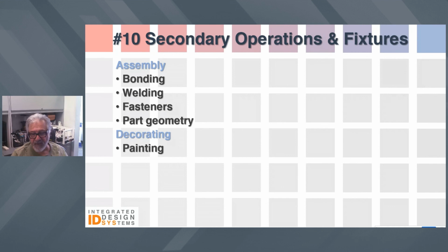And in the area of decorating, you've got paints, and paints have to be compatible with the substrate and the surface preparation of the part. So the parts have to be cleaned and devoid of any type of release agents or contaminants on the surface, so you get a nice, clean, uniform paint finish. Plating is another decorative, commonly applied method of decorating plastic parts. Then pad printing, and although it's very versatile, the alignment of all the colors and how the parts are fixtured and held in a pad printing press is a critical consideration in your documentation and in your overall design for an injection molded product.